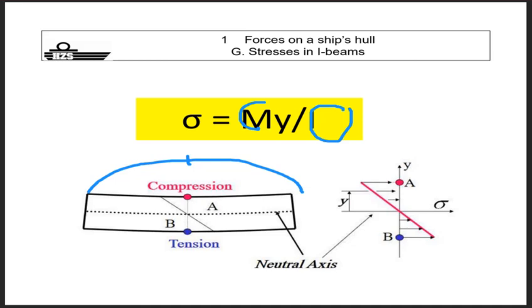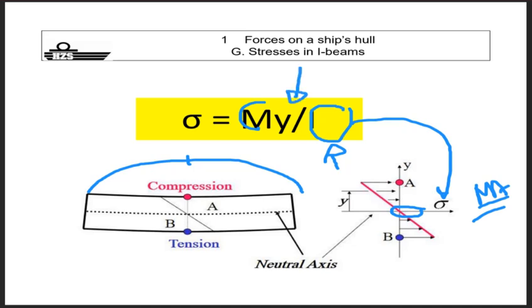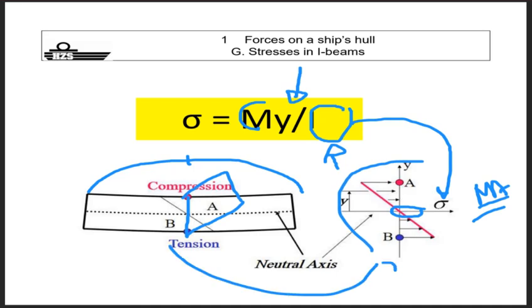Not every vessel with a certain shape has the same resistance against bending, and that's incorporated in your moment of inertia. Of course, you need to know where your neutral axis is located because you need to calculate this around the neutral axis to have a valid outcome. And then, of course, to know the worst case scenario, you need to take into account the furthest distance away from the neutral axis. So here, suppose you have indeed this cross section, like it's stipulated there.